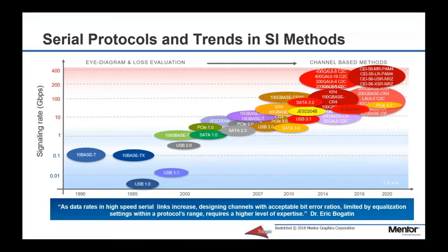Unlike double data rate or DDR technologies, which evolved over an extended period, SerDes technologies have evolved very quickly. There are only a few DDR specifications, but there are over 130 SerDes specifications, with speeds approximately doubling with each new generation. Most hardware engineers understand timing, have designed DDR interfaces before, and know how to make setup and hold margin measurements. But SerDes is a new ballgame.